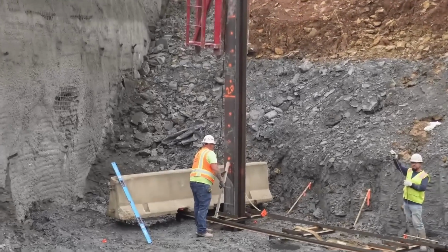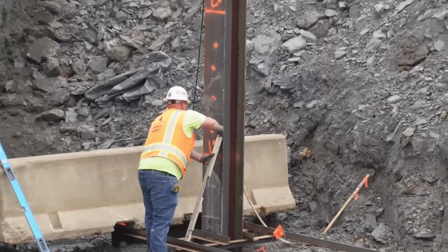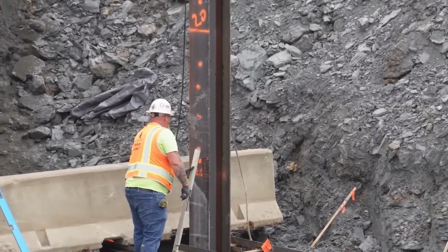This is a typical PDA test. This job is on the US 69 Tollway project in Overland Park, Kansas. You can see they've got clay fill over shale bedrock, and in this case they actually pre-bored to get sufficient pile length below the ground surface. That's to provide sufficient lateral support for the piling. The pile buck is there marking the set, so basically he's marking every 5 blows, and that's an important parameter for our subsequent analysis and for verification for the other piling that are driven that aren't subject to dynamic pile testing.